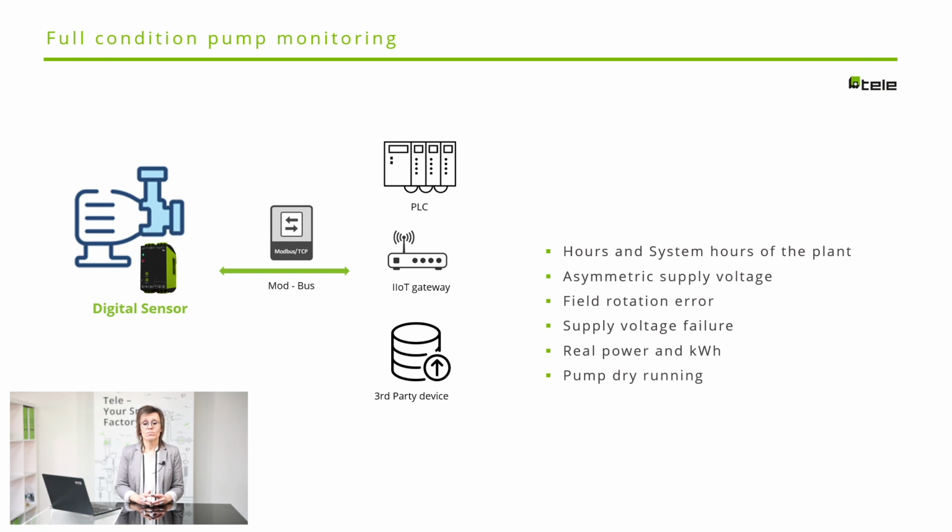Your USPs: supply monitoring and power monitoring are realized in one device. Counters are replaced by the unit. This unit can be connected to the cloud and therefore generate long-term data for energy consumption and water volume used per season, day or weather situation. Local alarms can be enabled to prevent the start or to stop the pump due to many alarm scenarios. Voltages can be connected directly to the digital sensor. The current is measured with current transformers and therefore there is no power limit for the digital sensor, which means one unit for all applications.